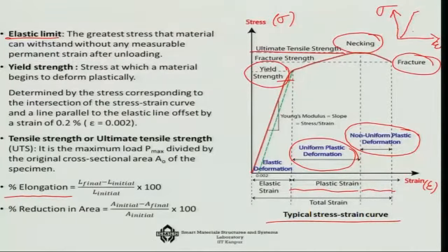The other important point here is that generally for the yield strength, if you do not find a very sharp point where this is happening, we consider approximately the 0.002 level, that means the 0.2% strain level. We find out where it is intersecting, and that point is defined as the yield strength level, because that is generally the strain level which it can take in metals without any permanent deformation. But this is very specific to the metals. For things like elastomers or rubbers, this can become something like 5% to 10%. So, depending on the material, this position changes.